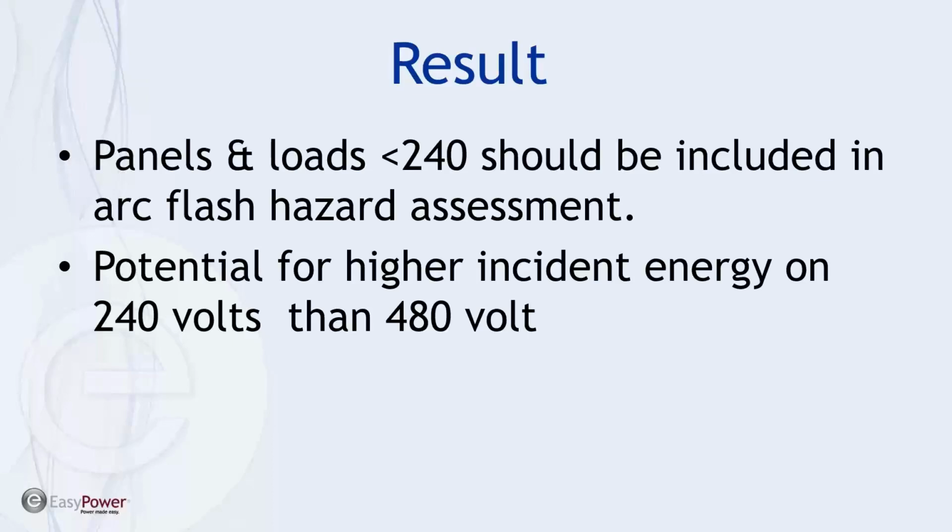Okay, we'll take that half step further. Those of you that haven't heard of the 2 second rule, when you see me get into EasyPower again, very frequently I'll see 2 seconds applied across the board, and the only reason I drag my feet on recommending that is that potentially it could interfere with my coordination. So before I do a mass limitation of 2 seconds across the board, I suggest making sure I have the coordination figured out for my system and the downstream loads before I start limiting any calculation period.